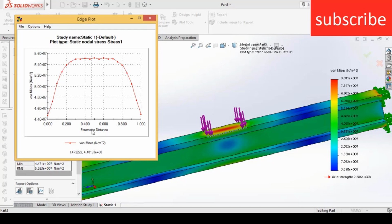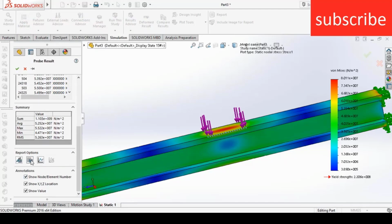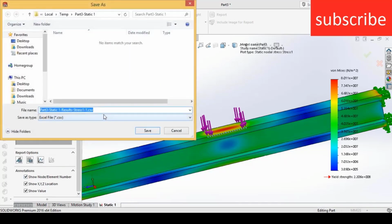Here a question arises in your mind. The stress is basically plotted in von Mises stress and parametric distance. Parametric distance is nothing but what I told you previously, the mesh length, width. Remember, this is what the graph plots. The number of triangles here, it plots basically on that. That is what is static nodal stress. Or you can save this file and use it in your Excel or sheet or somewhere as per your requirement. You just click on save, and you will get that.